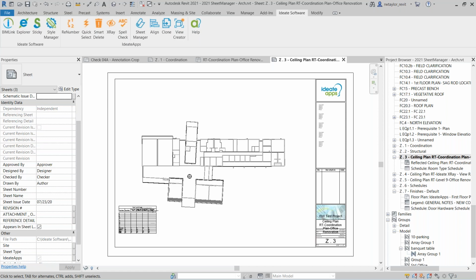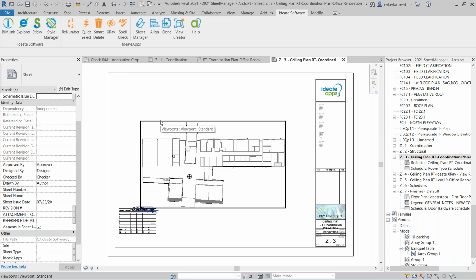Will the numbering of the room take into consideration the new room? That's a great question. So it's not dynamic, meaning that as you're modifying the room situations, it's not updating it. So what you'd have to do is, if that line crosses the rooms, let's say you split it, as you said, and you divide one room into 2, then you would just click on the line again and renumber it, right? At that point, it's renumbering based on that new room that exists. That was 1 room, now it's 2 rooms, and it'll just redo the sequence.